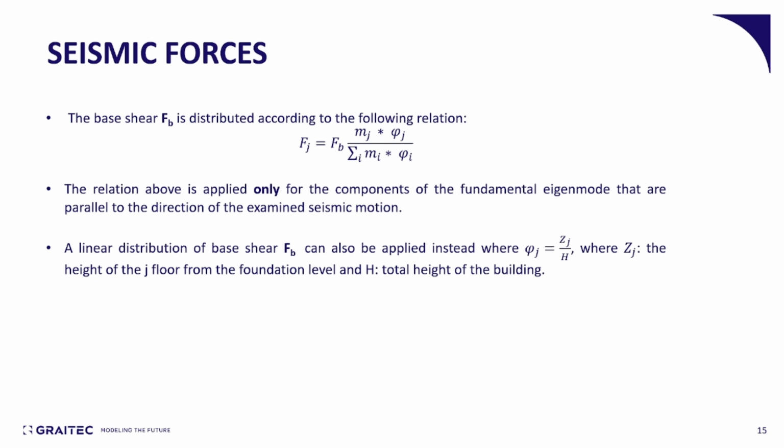So instead of calculating the lateral force by this parameter, we can calculate the lateral force that is applied on each floor based on this factor multiplied by the base shear.